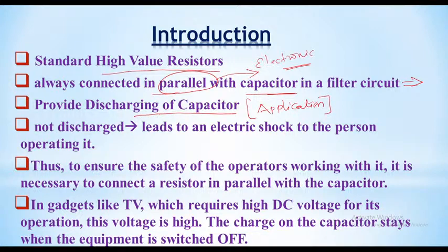Why do we need to discharge the capacitor? We already know the capacitor stores electrical energy. The capacitor will not discharge the electrical energy immediately. So this bleeder resistor is helpful to discharge this electrical energy completely. It is the major application of the bleeder resistor.